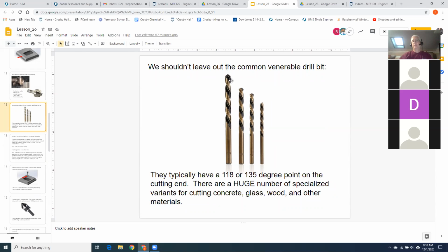So for those of you that are still insisting on cut extruding circles to make holes, if you send that off to a manufacturing guy, they're going to pull out this tool to make the hole. And it's going to have a coned point at the bottom of the hole. And then they're going to come back to you and say, do you really need me to mill that hole?